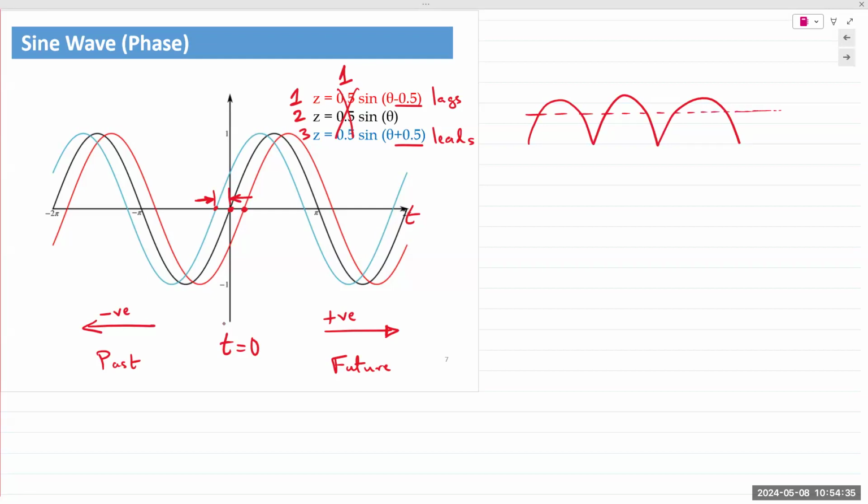You get a value that is equal to that DC value that would generate the same energy, or deliver that same energy. Does that make sense? So they had a problem at the beginning, meaning how can we mathematically describe this? Because if you take the average, it's just 0. So they decided instead of taking the average of the waveform, we'll first square the waveform and then we'll take the average.